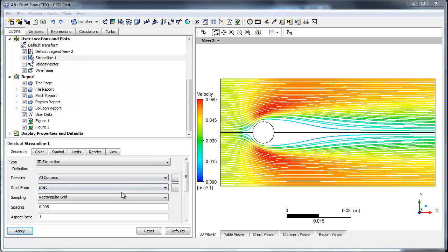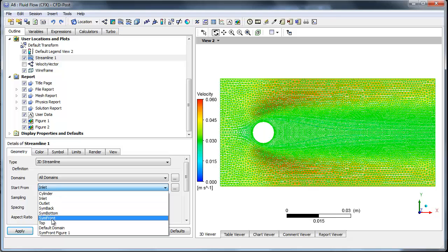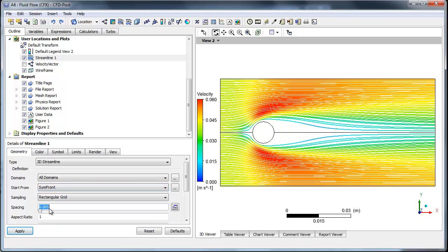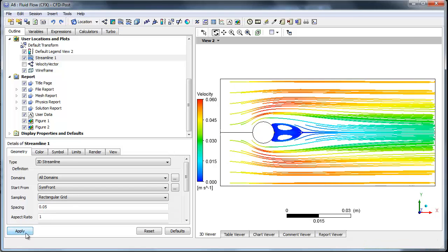Okay, you just have to use trial and error to figure out how this works. Actually, I think what I need to do, since I'm doing a grid now, is I want to grid the front face. Change my spacing accordingly. There we go, and maybe aspect ratio, have that as well.